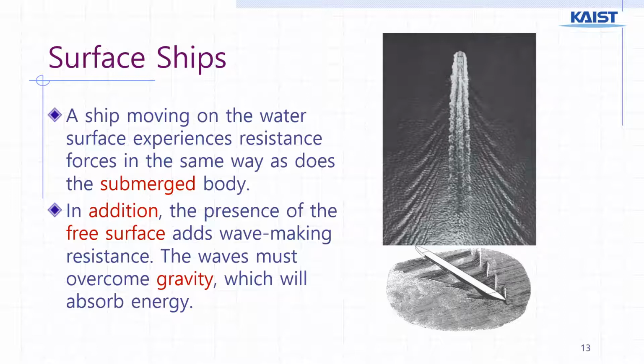So when the speed is high and the pressure is fluctuating, a cavity is formed someplace and then collapses, and forms, then collapses, periodically. So we call this the cavitation phenomenon. We'll see more in propulsion in a later stage of this class.